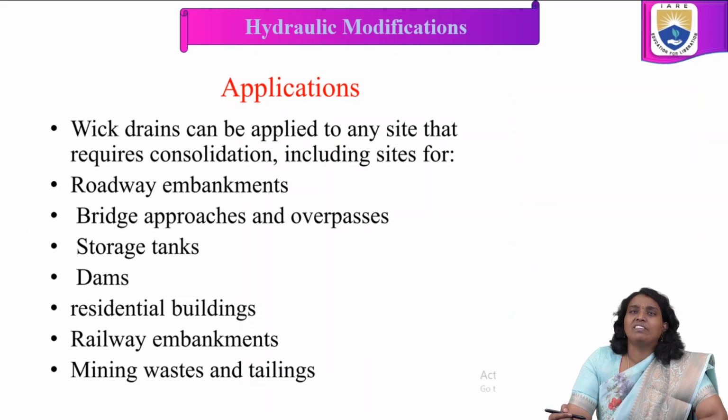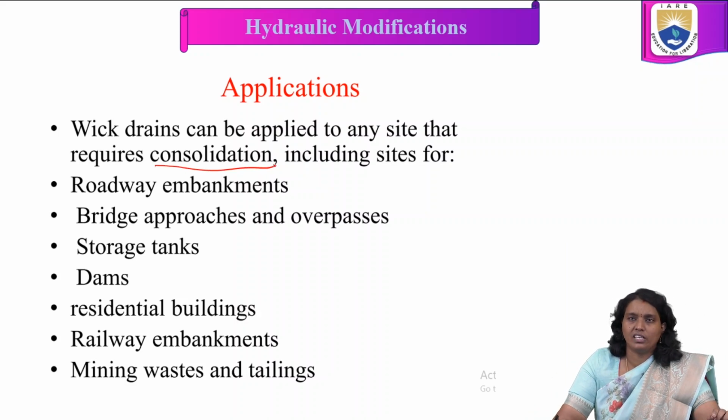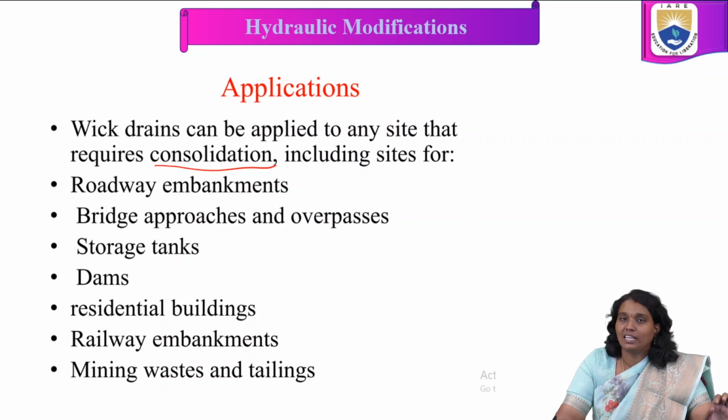Wick drains can be applied at any site that requires consolidation, including sites for roadway embankments, bridge approaches and overpasses, storage tanks, dams, residential buildings, railway embankments, mining ways and tailings.